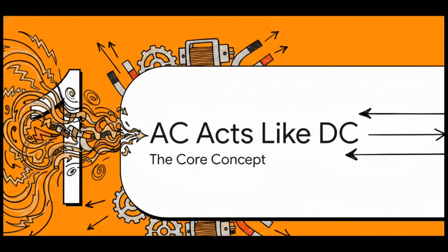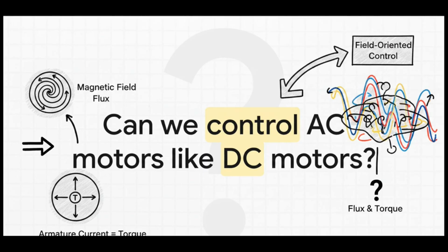Section 1. Making AC act like DC. So here is the absolute million-dollar question. How on earth do we take a complex, chaotic AC motor and control it exactly like a simple, separately excited DC motor? You see, with a standard DC motor, control is wonderfully easy. The magnetic field flux and the armature current, which is what actually produces the torque, are completely independent of each other. You want more torque, you just pump more current into the armature. The magnetic field doesn't care, it isn't disturbed at all.